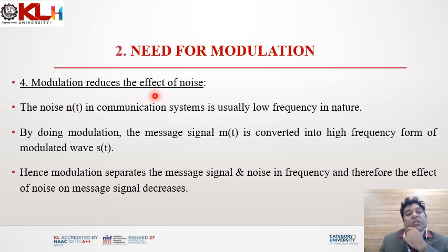Finally, modulation reduces the effect of noise. The noise in the communication system, N of t, is usually low frequency in nature. By doing the modulation, the message signal is shifted to the high frequency range. Therefore, by the modulation process, the message signal and the noise get separated in frequency, and therefore the effect of noise on the message will be reduced.